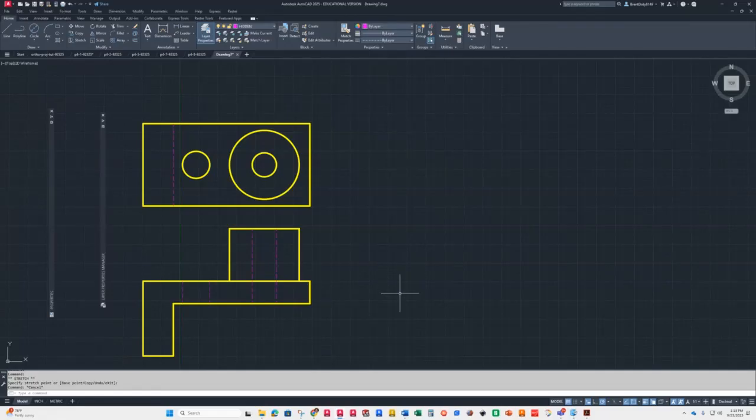And so we can kind of project things over. So this one also does not have a miter line option. So how do you draw a miter line off of it? Well, honestly, it's actually pretty easy. You could draw it over whatever distance you want and then go up at 45 like so. Well, how do you know where the other view is? Well, it's pretty simple.